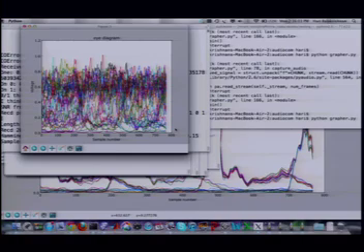Uniform noise? Yeah, you mean if you were to make another transmission at exactly the same frequency. The beauty of this is that there are different demodulation schemes. Right now, we're using something called envelope demodulation, which Professor Verghese talked about before. All that's doing is taking the absolute value of every received sample and then running a simple averaging filter. And that's what you'd write in the lab. It's a very, very simple demodulation.